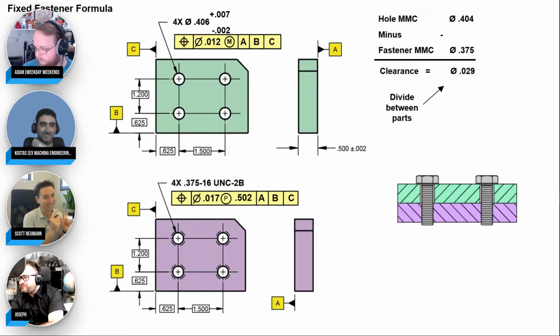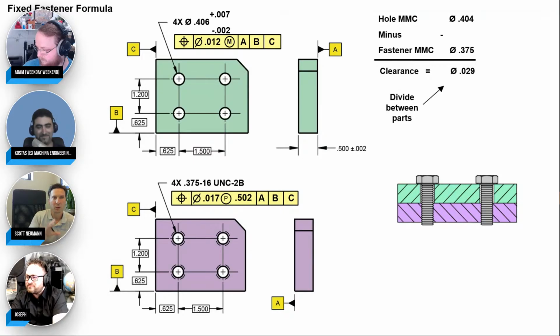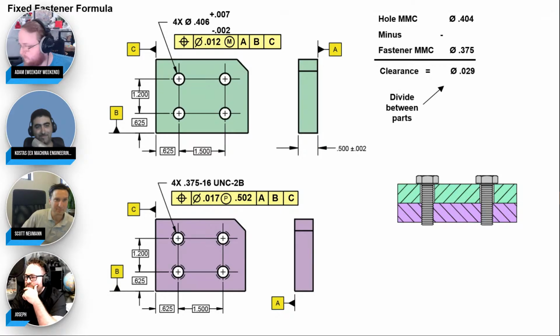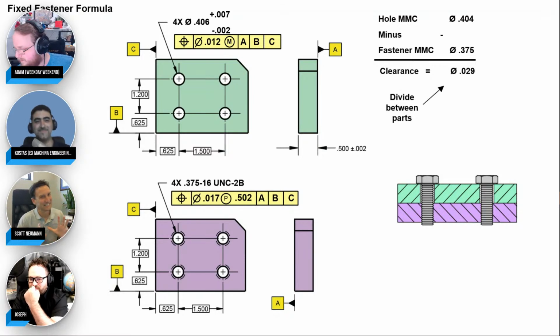But I'm not changing my drawing, because the next person wants to use the thread gauge and do it properly. So I want to give them the full 17 possible. So what I say is that's a quality plan, and we guard band tolerances. Guard banding is where you artificially reduce the tolerance to protect your hard boundaries set by the drawing. So cool, you do that for now. But then as soon as we get an upgraded CMM, we go to the full function. And then I don't have to go back to the design engineer and ask, hey, can we get that 17 back on the function again? Sorry, that ship has sailed. We're back at 15. So yeah, I really like to stay functional. And then quality, yeah, you do your thing.